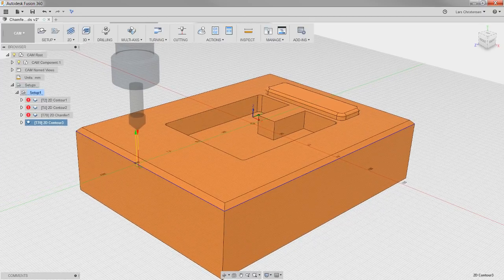I hope that this was not too confusing. So first of all, the 2D chamfer tool will avoid any intersections, so it will not gouge your part. That's awesome. But if you already have the chamfers on the part, then don't use that. Then you will use the 2D contour. As soon as you select a chamfer tool with that, it will turn those boxes on where you can adjust the chamfer.